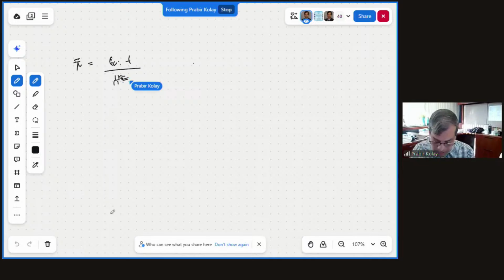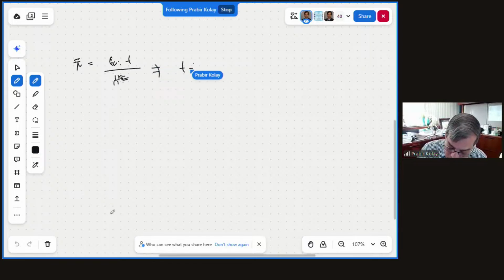I don't know why, the pen is very erratic. From here you can easily find out the value of t. Tv we just calculated from the degree of consolidation U equal to 25%, that is 0.0491 is equal to Cv.